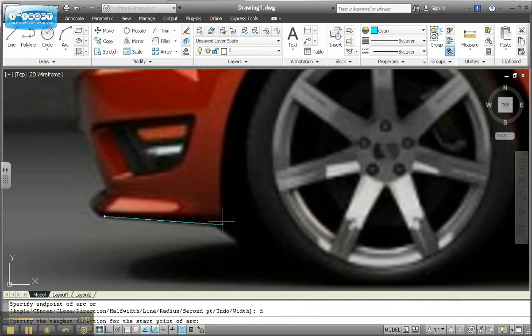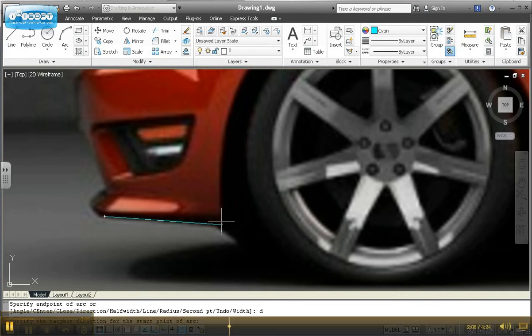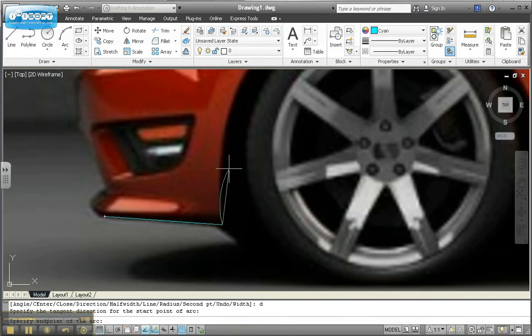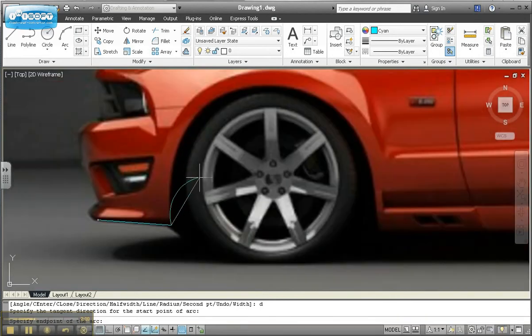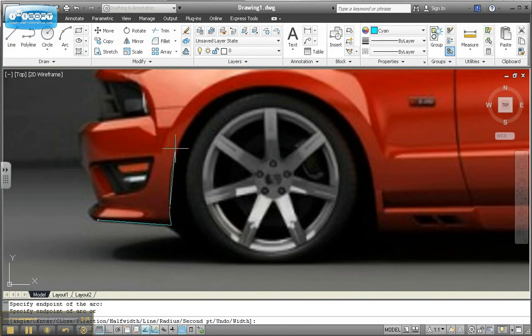Now I'm just going to make a tiny little click up in the direction of my arc. So notice I made a tiny little click. Now I'm going to zoom out so I can see my entire wheel well. So my next click, I'm going to make just a little one again in the direction I want to go. And there we go. And now my computer is starting to kind of recognize my arc. So you always want to match up the arc with the direction that you're going. And go. And this next click I can make just a little bit bigger because it matches up. And I end down here.